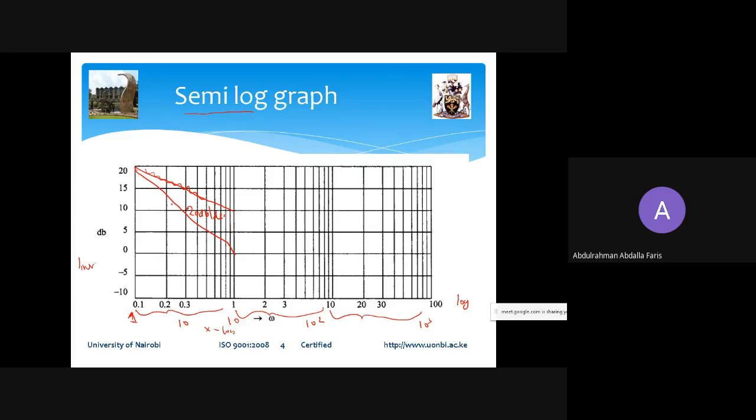First, you draw these lines as your key, the -20 and +20 dB lines, and then when you need them, you slide with a ruler. You construct a parallel line with that, just sliding with, I think, a square ruler.